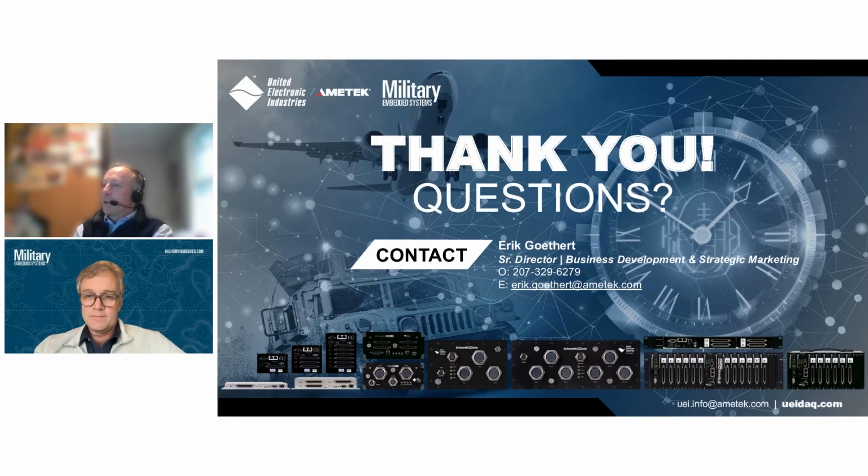Okay. Next question. Where and how is the clock signal generated? So typically what you have is a grandmaster clock that most of the time is synchronized to a GPS satellite. It generates the data packets, the UDP packets that run around the network to keep everybody synchronized.